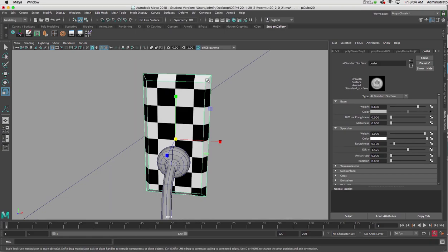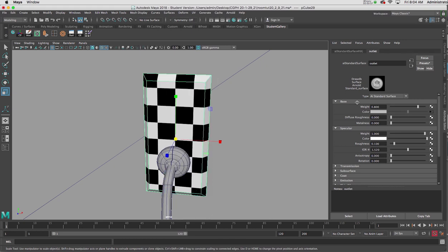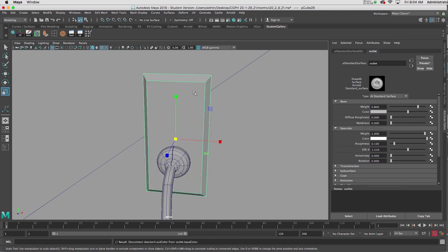Now that I'm back in, I'm selecting my geometry, and I'm going to right click and choose Material Attributes, and over in my Channels box that texture node will appear. Now I'm going to go down under the tab named Base, and there is Color, and that little black box with the triangle in it over here represents that checkerboard pattern we applied in Maya to get our reference and our UV map for Photoshop. I need to disconnect this checkerboard now to add my own texture. I'm going to right click on the word color and choose break connection, and my geometry turns gray again.